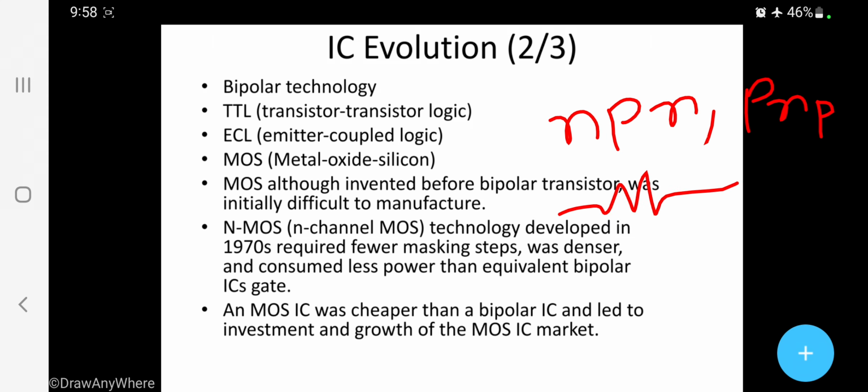And even if you require resistors and capacitors, along with NPN and PNP transistors, you can design them with the bipolar technology. It is a little tough to have capacitors and resistors with the bipolar technology. Using MOS, that is easy, but the area occupied is going to be very large, which we'll see within some minutes. So bipolar technology used to be there.